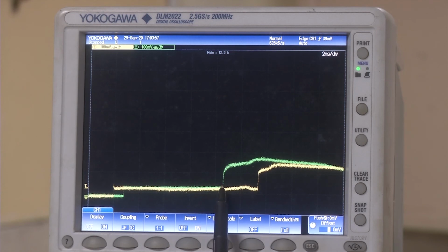So, that is what it sees, the reflected shock first, and this reflected shock keeps on rising, and at this particular time it means that the entire induced mass has a further rise in the pressure. That means, after this particular time scale the entire flow event is over, and this means it is the arrival of the contact surface followed by the driver gas. So, there is a sudden rise in the pressure.